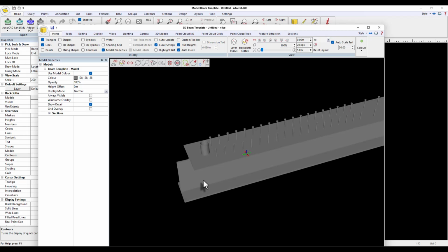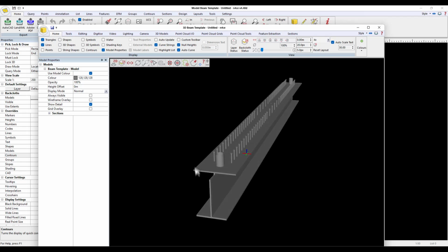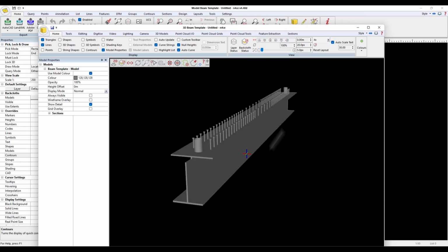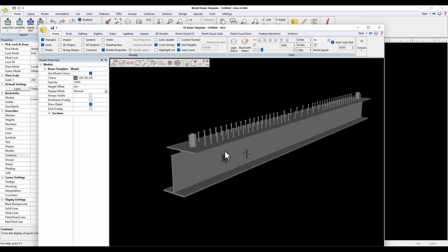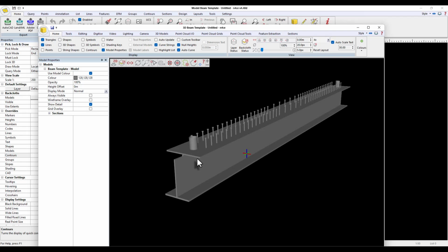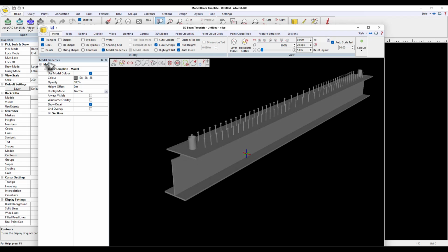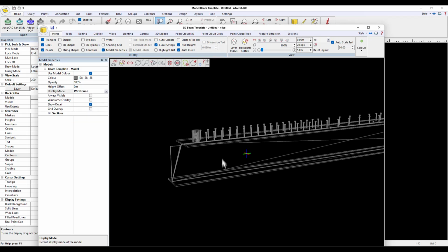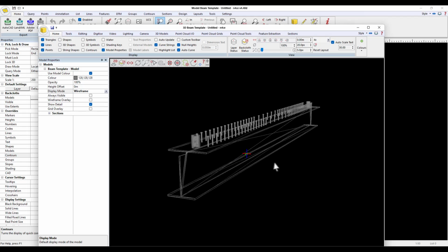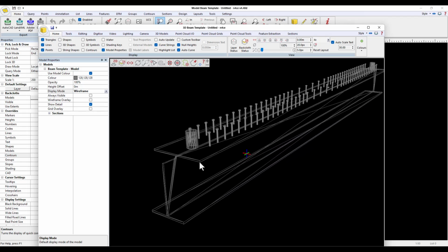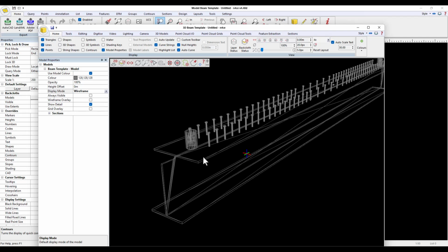So we're going to use this and digitize points on it so that we can then move or transform the point cloud into the same coordinate space as this. Now when it comes to digitizing, we need to make sure we pick exactly the point that we want. The easiest way to do that is to code the points, because then they'll be drawn in the view. If I click on points here and put that into wireframe, we don't actually see any nodes. So for us to digitize or lock onto the physical points of this, I need the 3D view to see them as survey points.